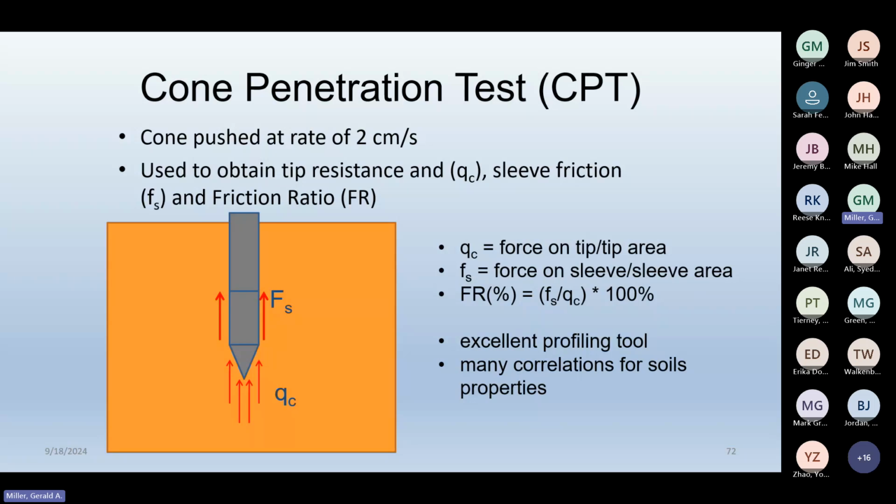Oh yeah, I know what I was going to say. I did a lot of this when I was a graduate student, a lot of piezo cone testing. I worked in New England in the Northeast, and the water tables were quite high. So we would always pre-drill a hole to the water table, fill the hole with water, take the piezo cone out of the water; it was always in water. Once we desaturated it, it never lost contact with water or the fluid that we used to saturate the stone.